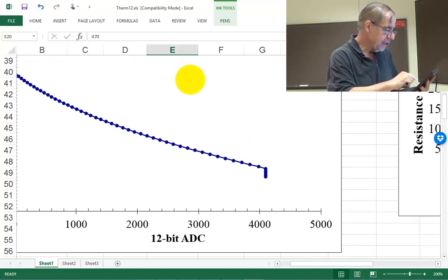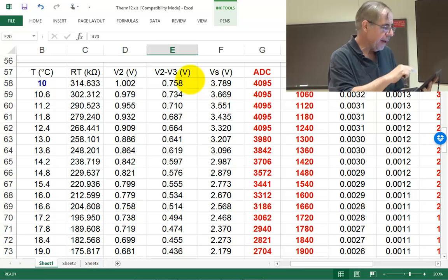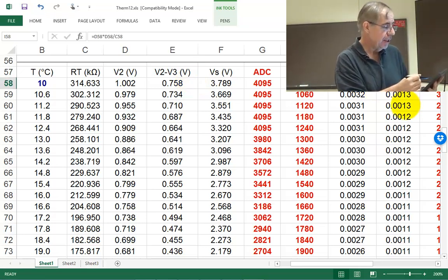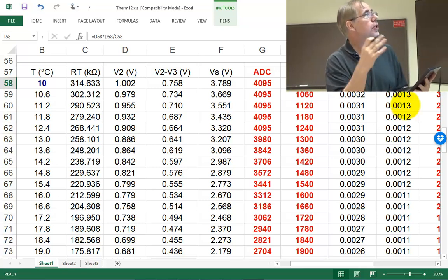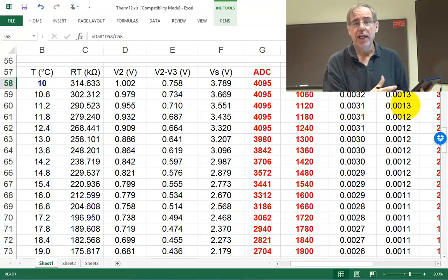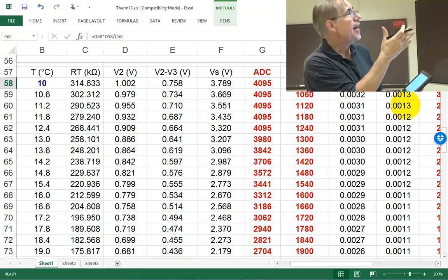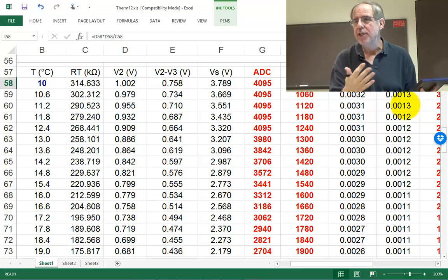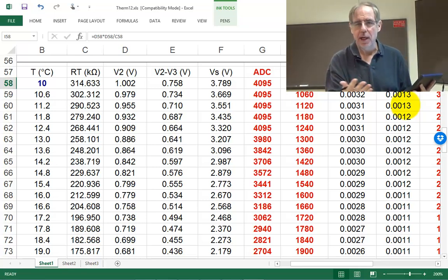That will specify how much power is in the thermistor in this column, and therefore the corresponding temperature increase in the transducer. You can see at 470 ohms, I'm increasing the temperature only by a millidegree, well below my measurement.